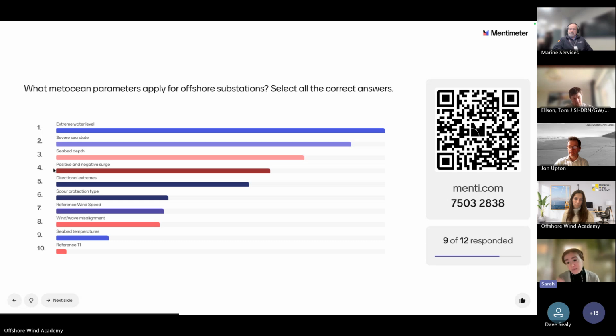Also, for deck height, because decks aren't designed for wave loading of that capacity. Of course, it's a human safety risk. You don't want waves to make it up where people have work surfaces. You also then on the other side have, if you have a very tall tower, boat accessibility as well. You want to make sure that you have a boat that has a height in order to be able to access the platform at that height as well.